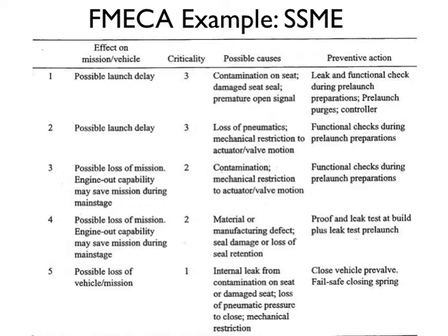Now, it may not really matter one way or the other for the most part, but I will say, though, that one of the important steps in the FMECA process is the review by the program and by individuals on the program. And it's important to set up the FMECA in a way that is logical to those people so that they can review it the most effectively. If it doesn't make sense, the value that you get out of their review will certainly be reduced. And that's something that, of course, you'd want to avoid.